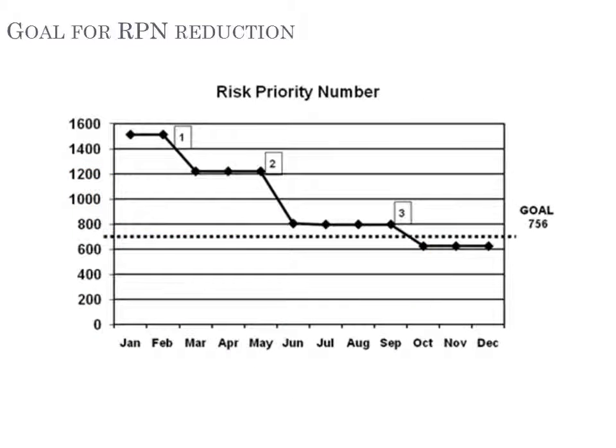When a potential failure mode is generated, the list of failure modes must be continuously updated. This results in a failure mode database which can be used for subsequent analysis. The failure modes should be updated when a new symptom of the problem manifests and should be dynamic to the latest symptom of the problem. The failure mode is the manner in which a component, subsystem or system failed to meet the purpose which it was intended to. FMEA occurrence and detection rankings should be evolved out of a long-term understanding of the issues and their revenue implications. The ranking given should be based on consensus.